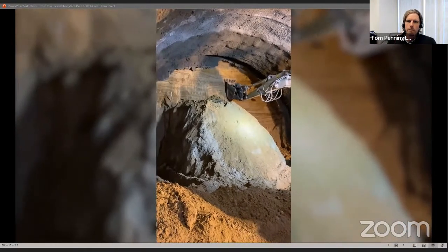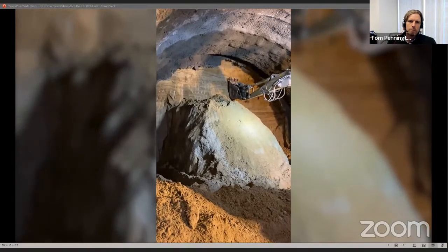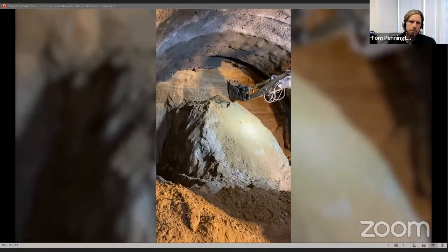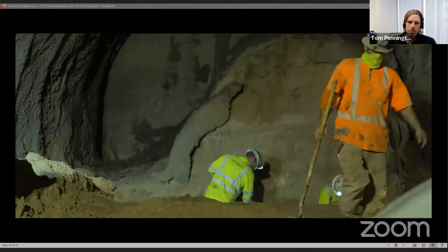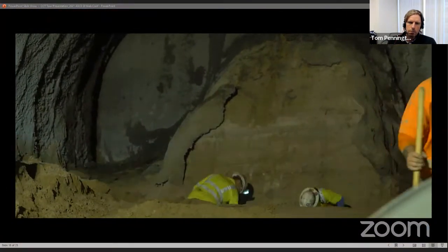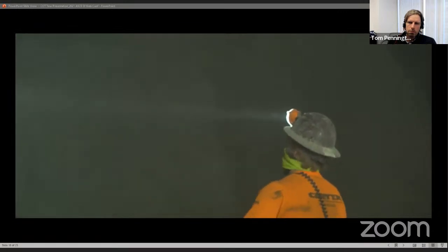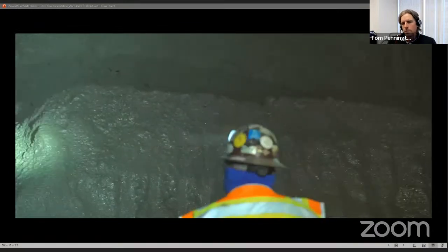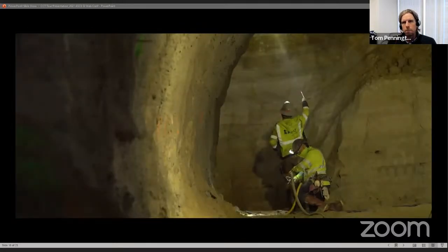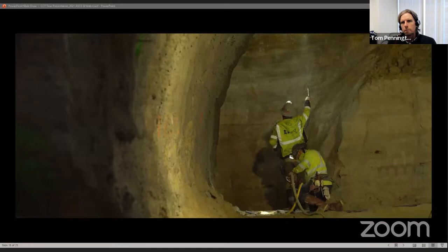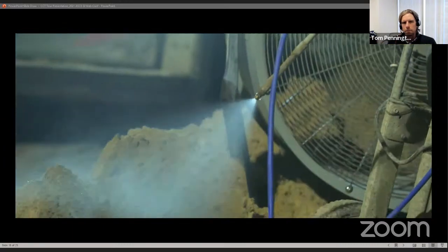At this location, the crown of the tunnel was a mere 7 feet below the bottom of a strip foundation for the building above. Despite the support of canopy pipes in this location, the tunnel excavation sequence was modified, and pocket excavation with flashcrete applied incrementally at the tunnel face was used to minimize the area of unsupported ground and better control ground movements. Additionally, the application of sodium silicate was used on the exposed sandy ground.